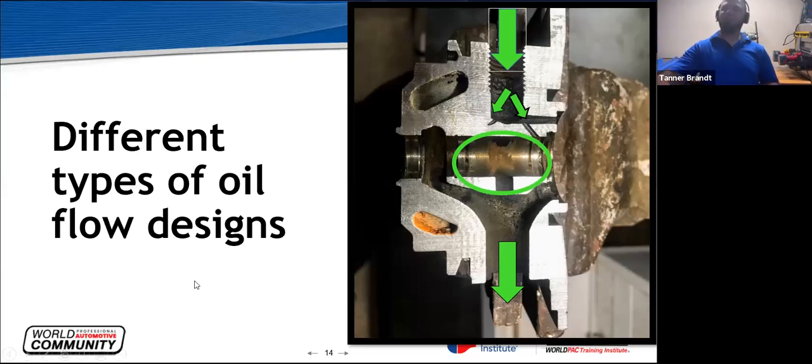All right, the other important thing to notice with this is a coolant passage right here. Coolant flows through the exhaust side of a turbo. The reason for that is to cool this end of it to help keep the oil from burning, sludging, and coking up. As you can see, this gallery is full of rust. Once that happens, you no longer have coolant flow going through it, and the exhaust side is going to get really hot. Then you're going to start burning oil and coking up oil on that side and ruining the ring on the wheel and shaft.